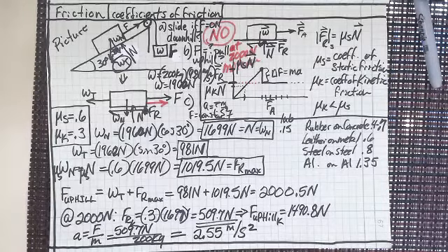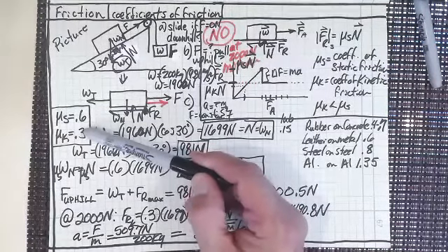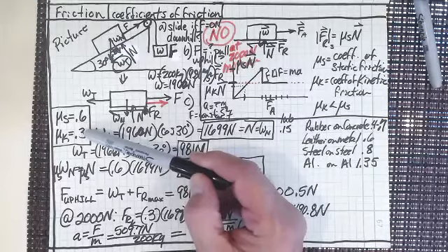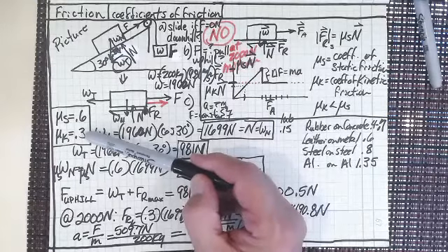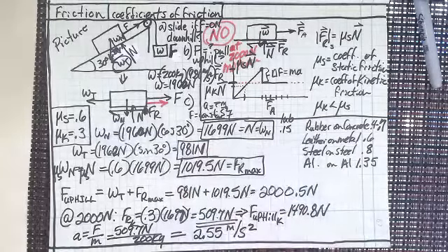It's almost like you've got something on a slope on a very rough surface, and then you've thrown oil in front of it. And that oil is just seeping underneath, and eventually it's going to cause it to start moving. Once it does start moving entirely over the oil, then it's going to go down to 0.3, and it's really going to slide. That's a huge difference between mu sub s and mu sub k. And that's what you find out there.